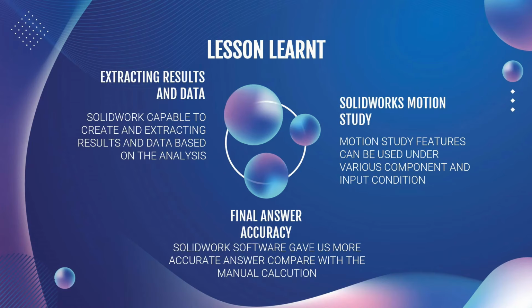Excellence in SolidWorks motion study. SolidWorks allows the study of motion with different components under different input conditions. In this assignment, the motion analysis is mainly used to execute the result. In addition, in motion analysis, velocity can be applied, plus the addition of gravity is useful for projectile motion study, which is also learned in the motion study. Lastly, results can be generated based on preference for the assigned problems and can be exported to Microsoft Excel to further analyze the data.